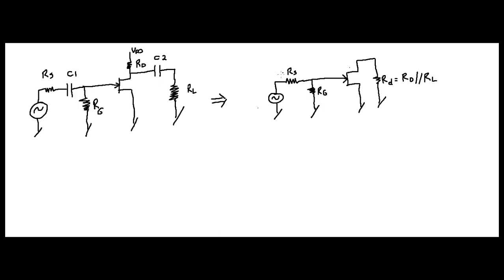Now, you have internal capacitance here of your device. That's going to be what really matters. So remember, you're going to have a capacitor here, okay? That's going to be CGD, gate drain. You're going to have a capacitor here.